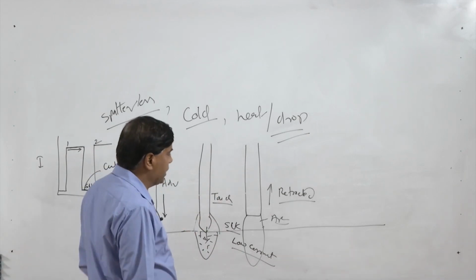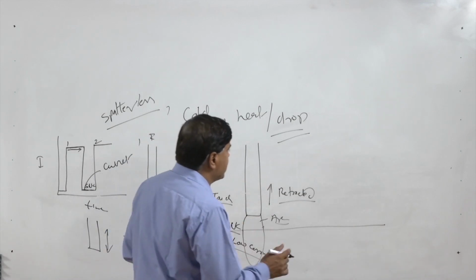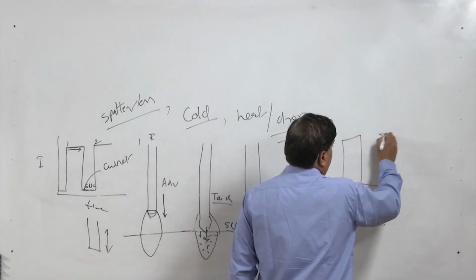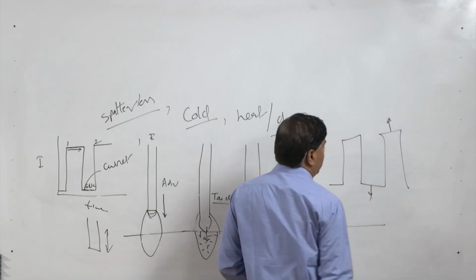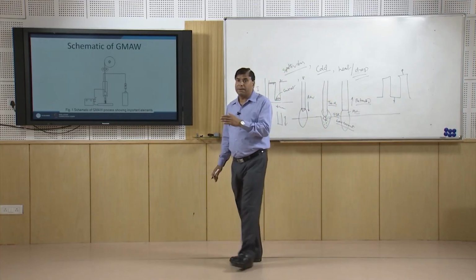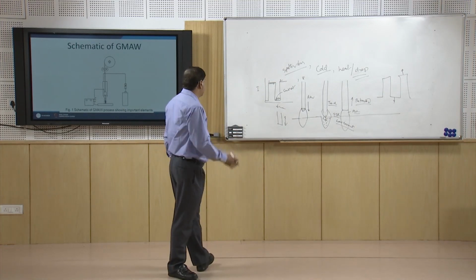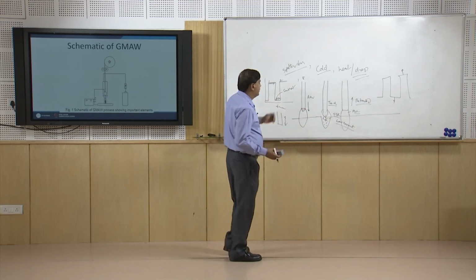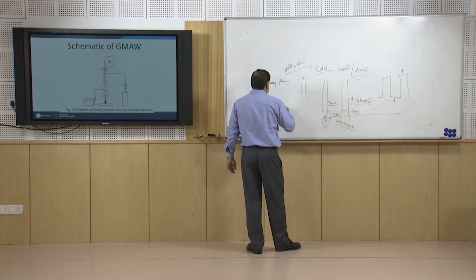This is the sequence which is normally repeated, and it is synchronized according to the pulses between the peak and the background current level. Here short circuiting takes place, and this is the peak current level. So, one pulse, one drop, this kind of synchronization is achieved for the CMT process, wherein after each cycle there is transfer of one drop.